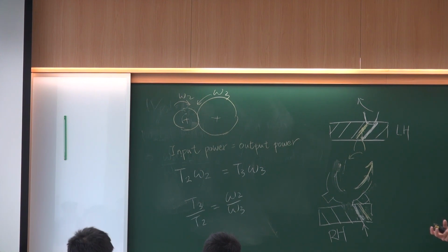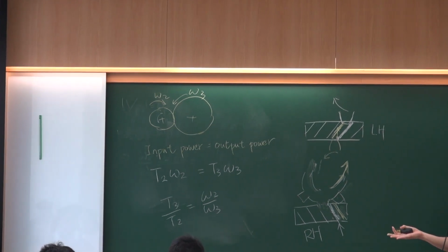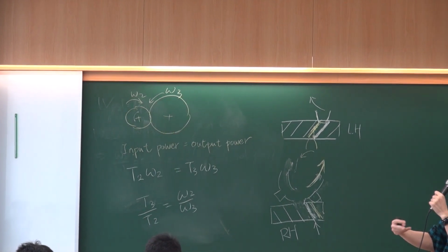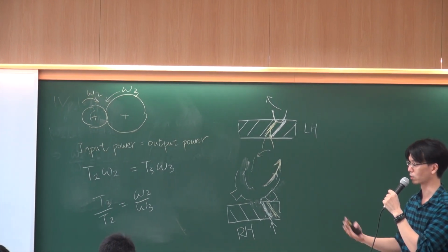Usually the motor cannot provide a large torque, so we will install what we call a reducer. Reducer means we are going to reduce the speed. But once you reduce the speed, you are going to increase the torque. So, not sure if you pay attention to an electrical car. Although the property of a motor is that it can have a very high rotational speed, the torque is usually not that large. Especially for a vehicle, we usually need a large torque in order to climb a hill or something.